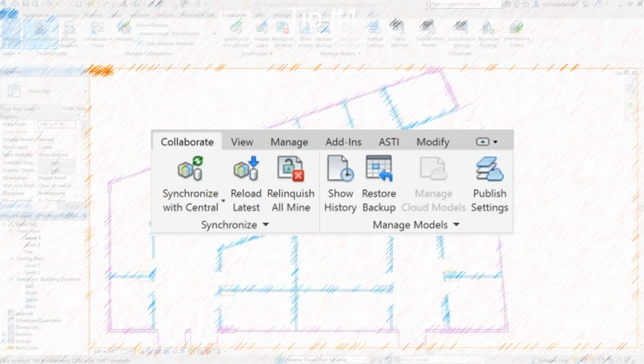Now, I mentioned backups or hiccups or mistakes or problems, because there's this thing that happens every once in a while. A central file goes corrupt, or your local file goes corrupt, or there are just problems, right? We just ran into issues and something's not working right. And we get these calls from people saying this isn't working right. So we can go to this little Restore from Backup, right?